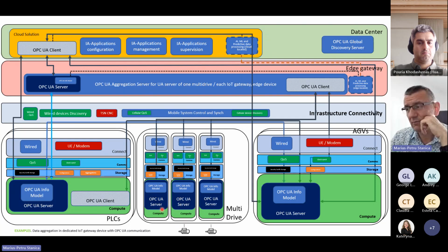For the PLCs, which you have just seen in the model, drives are working in the same way. The drive is something which controls the motor. Imagine that you have several motors running there, and a drive which connects to the power grid, like an input converter or a rectifier, followed by several inverters.